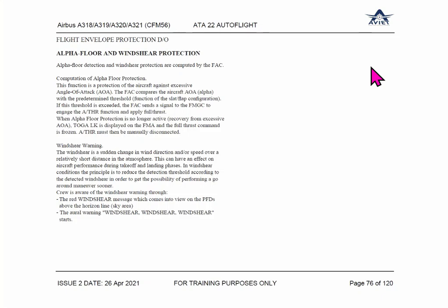Irrespective of whether it is auto thrust or manual thrust, wherever the levers are, it won't care. The FMGC will automatically apply the TOGA thrust. Correct? It will not see where your lever is. Whether your lever is at flex or climb or below the climb or above idle, wherever it is.